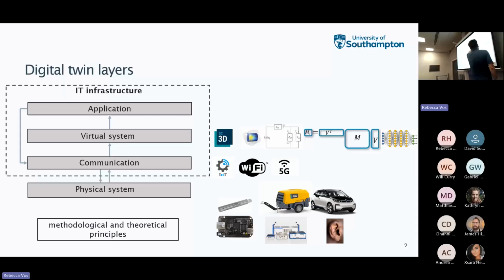But the idea is that finite element models, as most of you probably know, are very large, and they cannot run in real time on a machine like this, like Speedgoat. It's just impossible. So instead, we want to reduce the size of these finite element models so that they're still accurate, but much smaller, so that we can run them in real time if we need to.